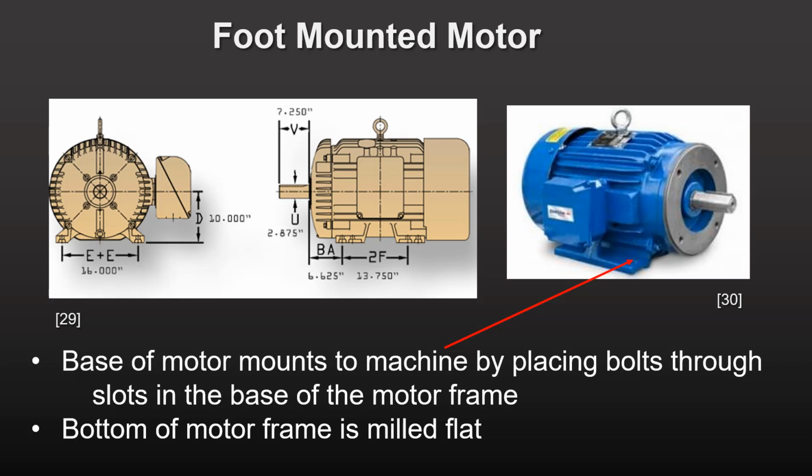The motor is mounted to a flat surface of a motor frame via a rigid flat surface on the bottom of the motor. You tap 4 holes in the frame, put in 4 screws, one each through the 4 holes in the feet of the motor, and your motor is attached to the machine.